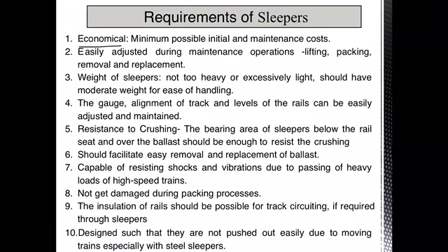The third requirement is that the weight of the sleeper should not be too heavy, nor excessively light. It should have a moderate weight for easy handling. If the sleepers are very heavy, handling will be difficult. If it is very light, it may not have sufficient strength for load carrying. The design of the sleeper should be such that the gauge, alignment and levels of the track can be easily adjusted and maintained.